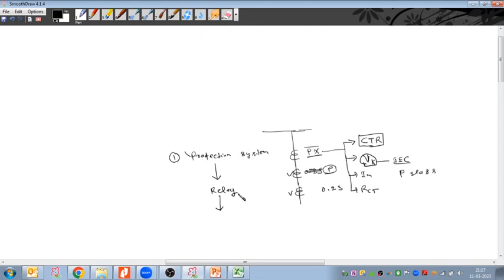Once the relay selection is done, and you know what make of relay you are going to use based on the protection system, then you download the relay application manual. There are many manuals for the relay, like the technical manual also. Do not download the technical manual. In the technical manual you will not find any CT requirement formula. For the CT requirement, the manual name is the application manual.